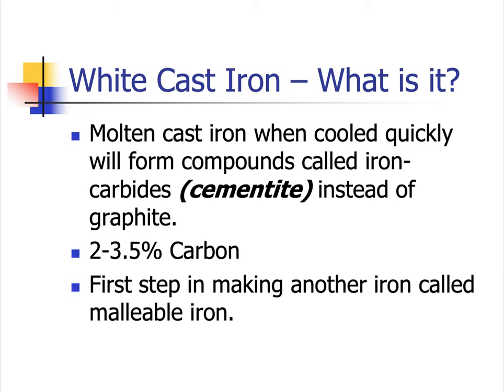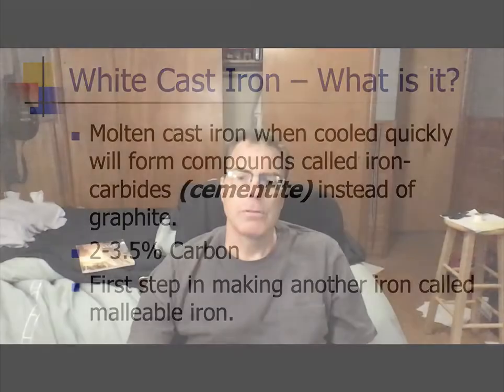So some applications that you could think of for white cast iron would be a pulverizer for pulverizing coal. I don't know if you know this, but when your power plant uses coal, it has to powder the coal first, and in order to do that, they have basically a big track with huge steel ball bearings, or white cast iron ball bearings, going around. So I work with a company in South Africa that makes really hard white cast iron balls.